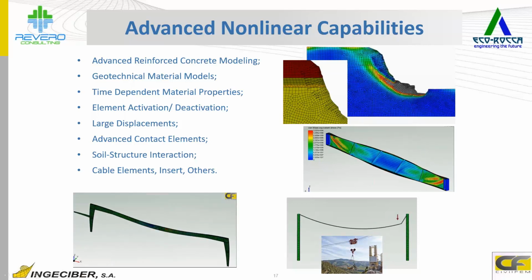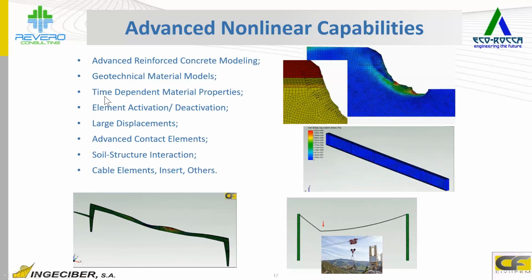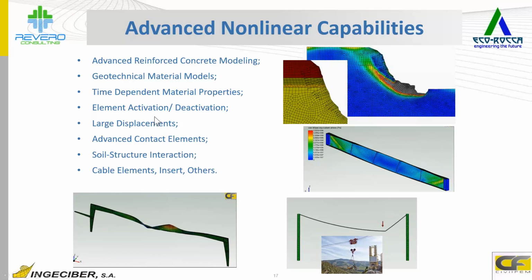As mentioned, Drucker-Prager, Mohr-Coulomb, Hoek-Brown, Cam-Clay, and recently hyperbolic strain behavior based on the Duncan-Chang model. We have the possibility of changing material properties in time, so it is a time-dependent material property. We have the possibility to activate and deactivate elements, which will allow us to